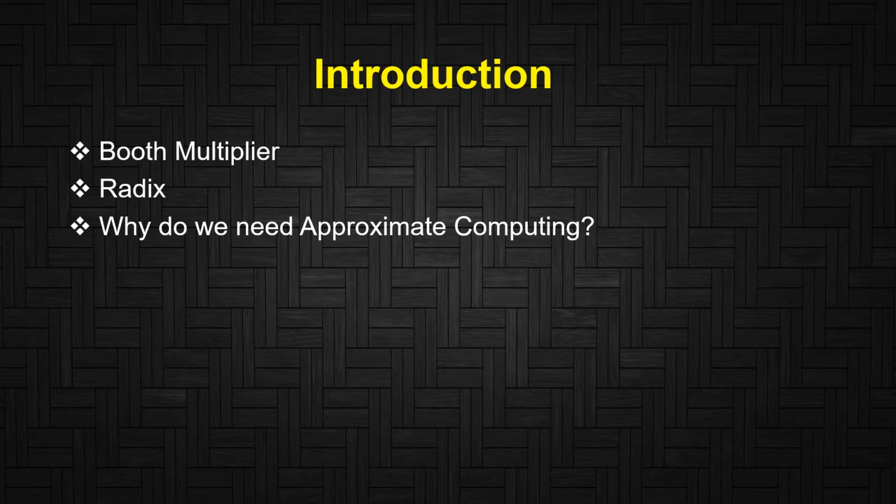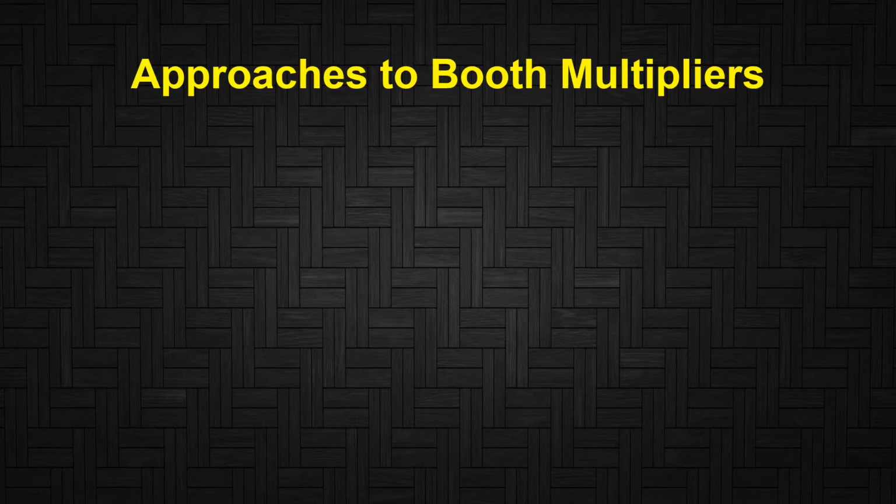Approximate circuits generally refer to the approximate design of arithmetic units, such as adders and multipliers. For quite a long time now, the fixed width booth multiplier has been studied. We also studied it in our class, and it uses a truncation based approach. Now basically truncation achieves the hardware gain which we are looking for, but it also incurs a large amount of error.